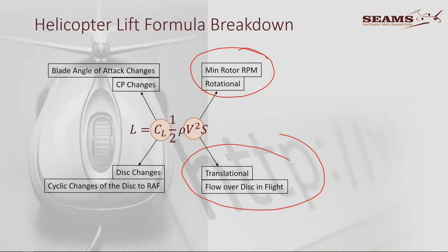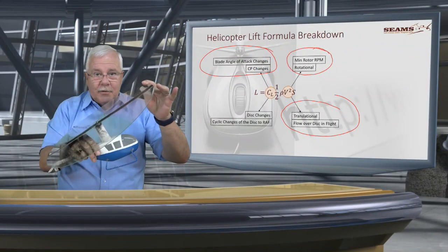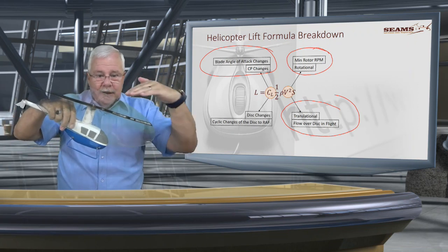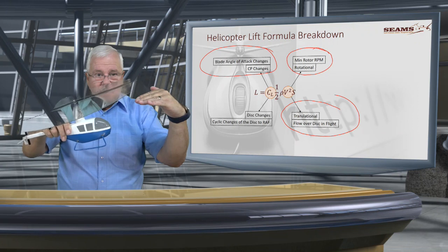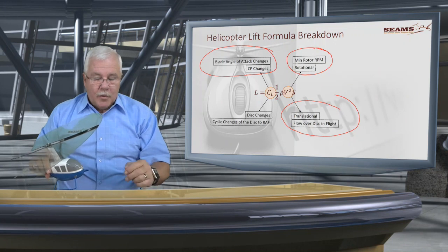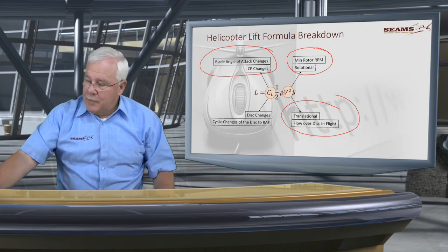The thing that we are looking at on the other side is we set the blade angle of attack through the collective pitch. That is fine. And then at the bottom, through the cyclic you can actually change the angle again. So if you change this, remember from here in forward flight, the wind is coming from here. Let's keep the wind constant, and you'll see if you manipulate the disc, the wind actually comes from a different side, and that changes the angle of attack quite dramatically. So we have to look at how to fix and manipulate that.